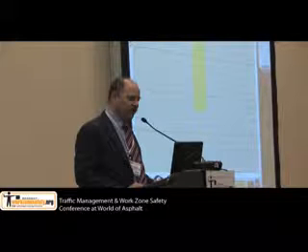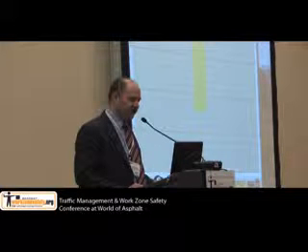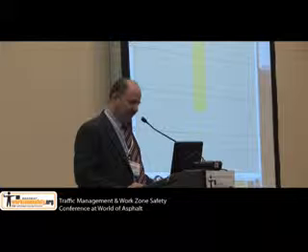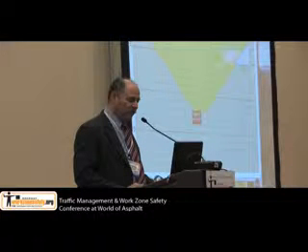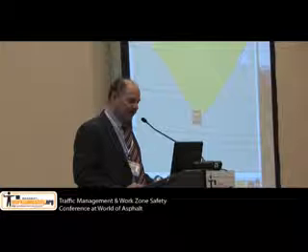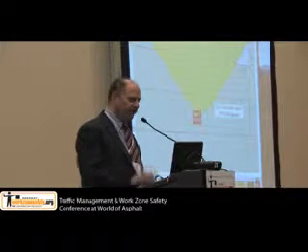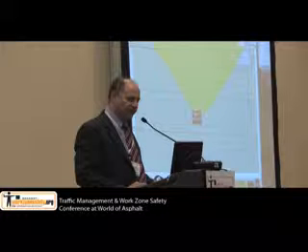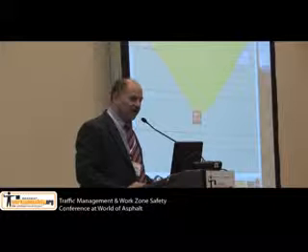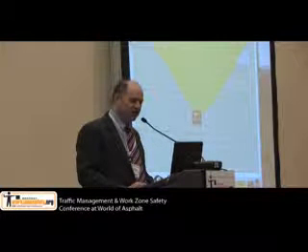And then you set how you're going to protect people. Say you're going to slope it. So it's a 1 to 1.5 slope, and it shows you basically you're going to need to excavate out 20 feet in either direction. And we have the cost calculator, cost per yard of trench length.